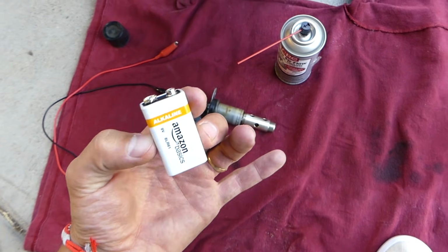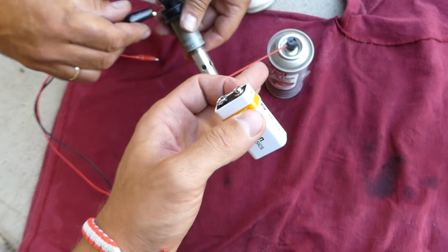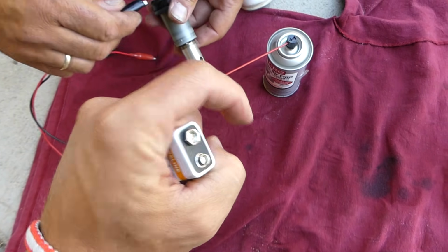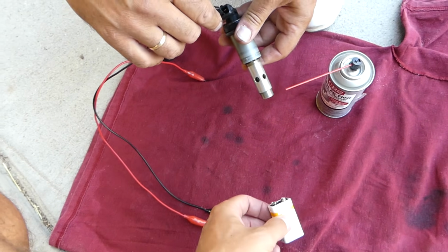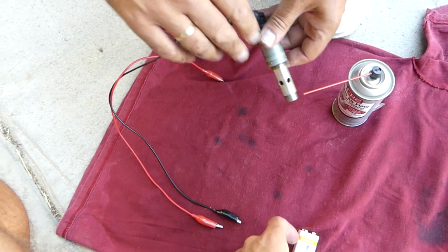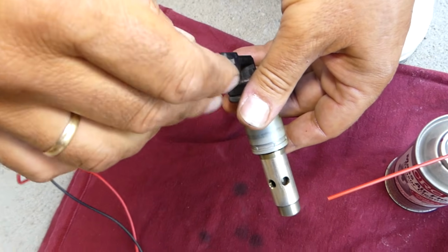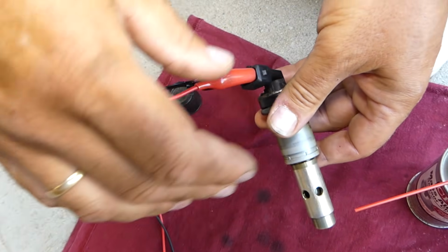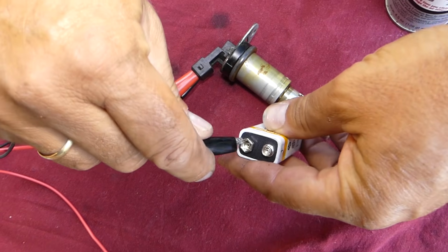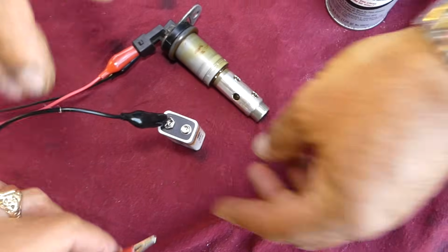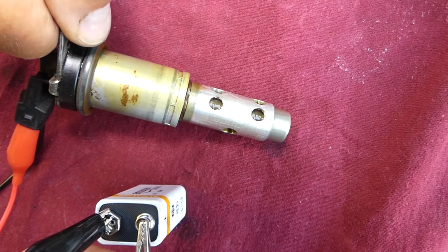Next guys, a 9-volt battery. All the links that we use, the parts that we use, will be listed under the video below. So we're going to connect with the alligator clips right here. They're very good because that way, let me show you, we cannot touch each other because otherwise you can burn your solenoid. Next we'll connect the negative cable to the negative of the battery. Okay, and after that, if I touch it, you'll see the solenoid moving.